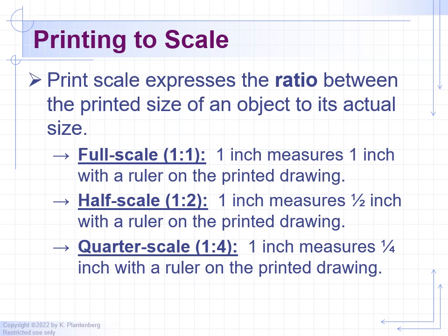That way, everything that's an inch on the object is actually going to be a half an inch on the paper that's printed out or in the PDF. Larger objects might be quarter scale or 1/10 scale, etc. There's a whole series of different scales, and essentially it's always going to be the ratio of the printed size compared to the object. So for example, in a quarter scale, something that was 4 inches long would actually only be printed out as 1 inch.